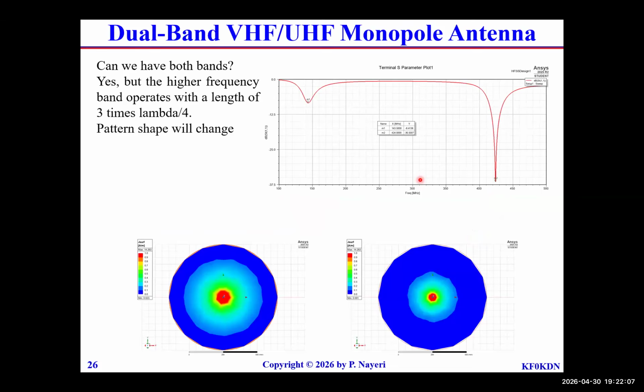Typically, increasing the radius of a wire antenna improves its matching bandwidth. And of course, if you're using a BNC connector and that 1 millimeter thick nitinol wire, then you can plug in those exact dimensions and tweak the wire size a bit. Note that the current distribution on the ground plane at the VHF band and UHF band are also shown here. You see that at the UHF band, you have a lot of edge current associated with it due to the larger size of this type of antenna.